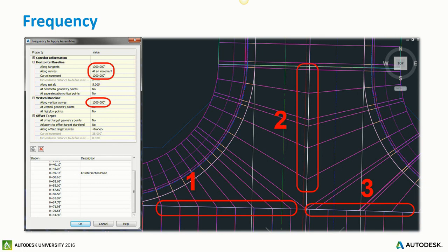You can see point number 3. You can see how the projection from the curb doesn't meet with the main line. Does it work? Yeah. So see this guy? These lines don't meet up with the main line. This is the corridor through the intersection. This is my curb, and these points don't meet.